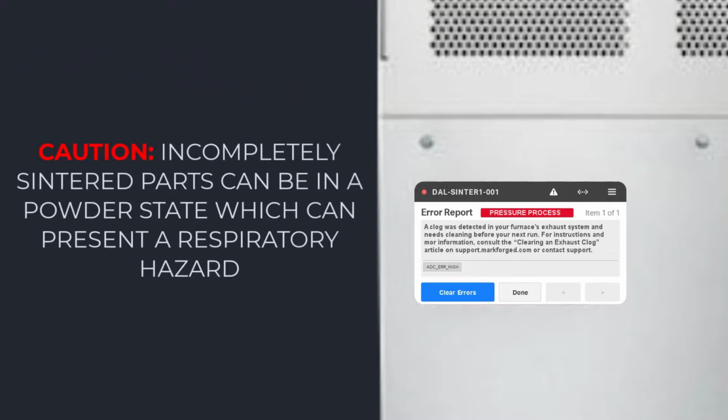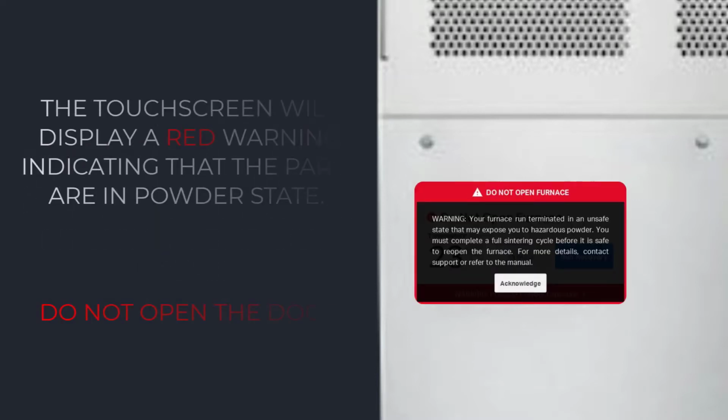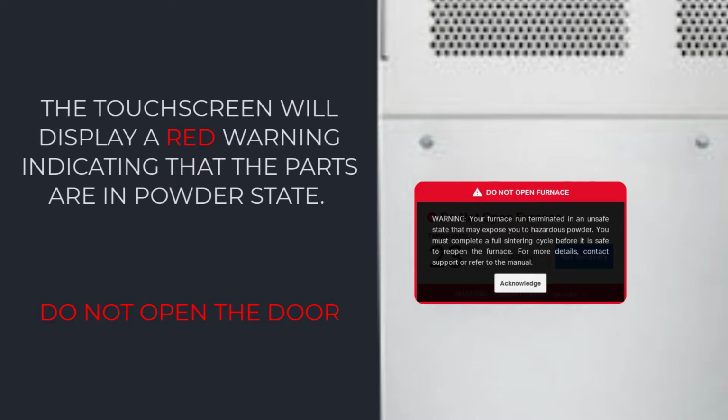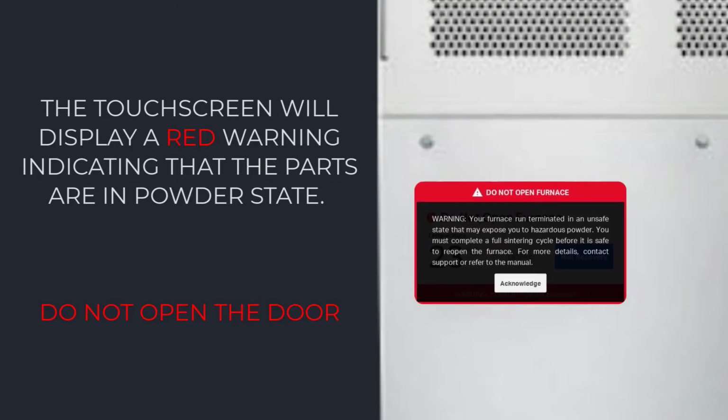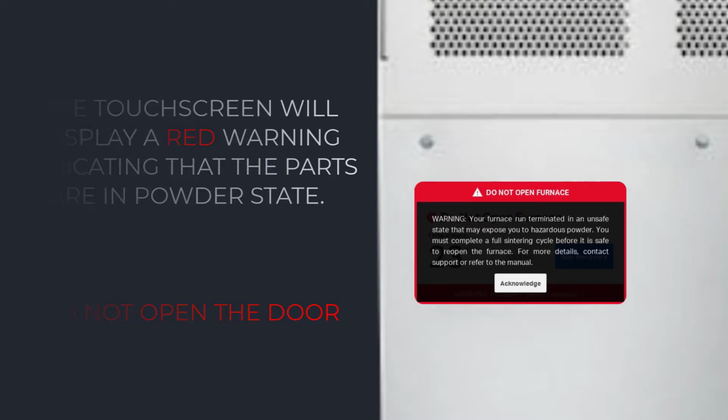Caution: incompletely sintered parts can be in the powder state, which can present a respiratory hazard. If a sinter run fails during the debinding stage, the touchscreen will display a red warning indicating that the parts are in a powder state. At this point, do not open the door.